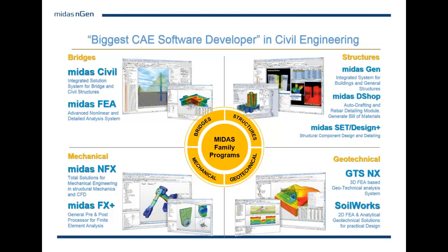Under the bridges, we have MIDAS Civil, on which we actually had a webinar session yesterday. We can perform the analysis and design of simple RC slab bridge, box culvert bridge. We can also perform the analysis and design for PSC composite bridge, steel composite bridges. We can have various construction stages included in it.